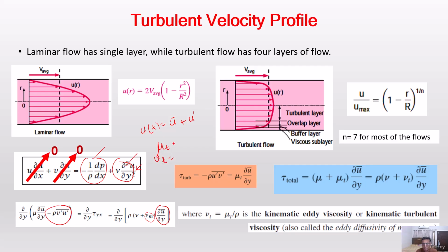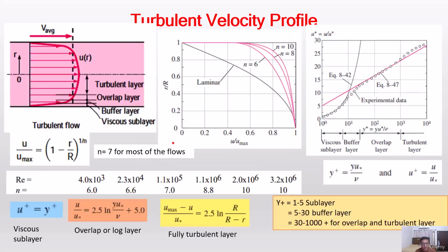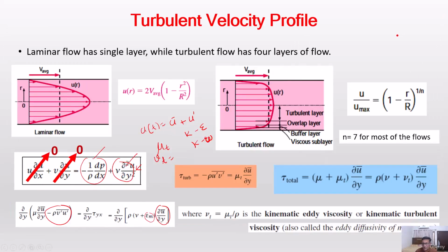That can be found from the various relationships in the k epsilon or the k omega models. And in the SA model, this is done with the help of the modified turbulent viscosity. So once we find these properties, we can put them in the formula and get the values for what we call the turbulent viscosity. Let me show you the formula for that.